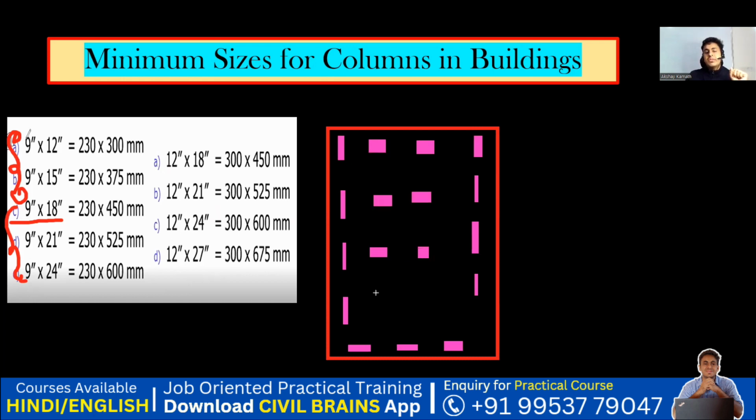So usually what happens, the columns which are in the interior, the columns which are inside, that is these columns, will be subjected to more load because, since they are in the interior part, they will be getting the load of the slab from all four directions. So in this case, there's every chance that you have to give a bigger size of column. Now let us say I have three sizes to choose from: 9 inch by 12 inch, 9 inch by 15, and 9 inch by 18. So these four columns, I'll go with 9 inch by 18 inch since they're in the middle portion and subjected to more load. I need to give a bigger dimension, right?